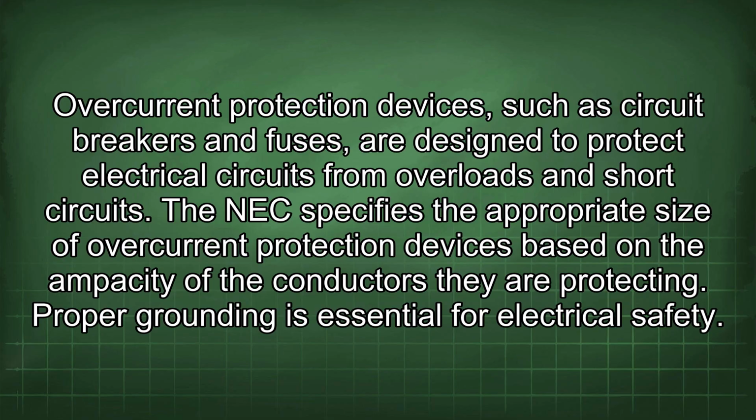Overcurrent protection devices, such as circuit breakers and fuses, are designed to protect electrical circuits from overloads and short circuits. The NEC specifies the appropriate size of overcurrent protection devices based on the ampacity of the conductors they are protecting.